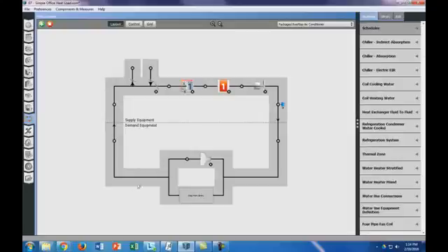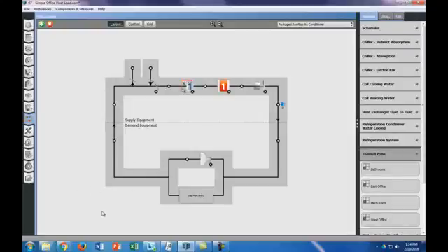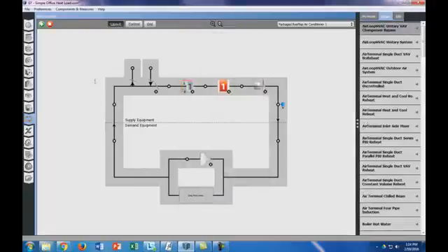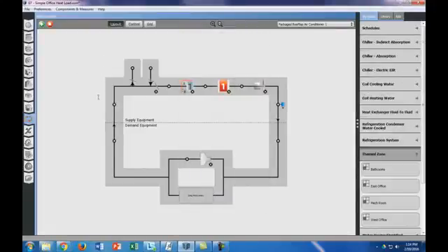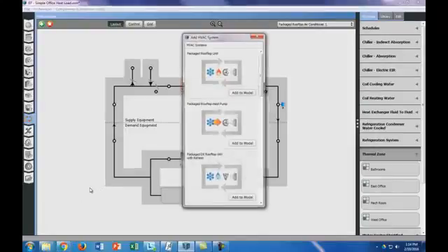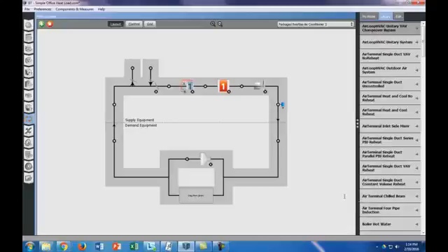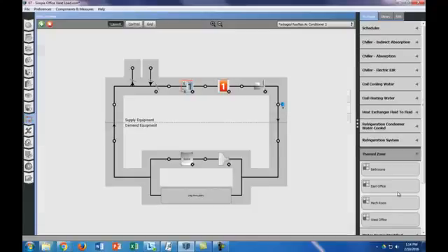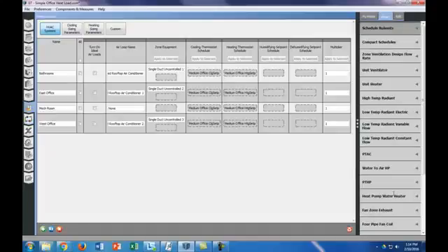Then we're going to go to our thermal zones and make one of these for each thermal zone except for the mechanical room. We'll do the bathrooms first, which is going to be a packaged rooftop air conditioner. Then we're going to make another one and go back to our thermal zones and do East office, and then go back to our thermal zones and do West office. The way you can check this is, if you go to your thermal zones, everything but the mechanical room should have a packaged rooftop air conditioner. And since we gave it an HVAC system, it actually turned off ideal air loads for us.